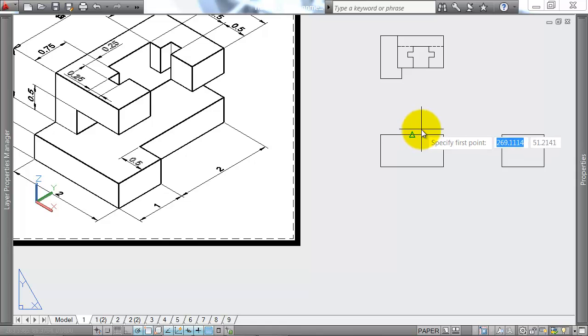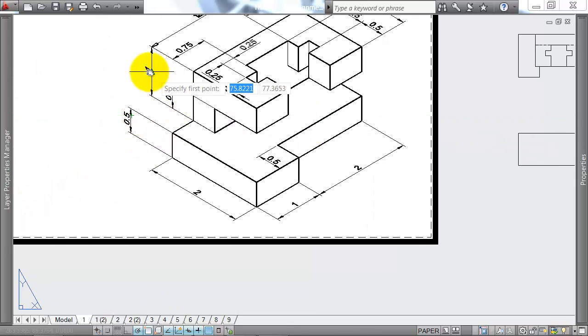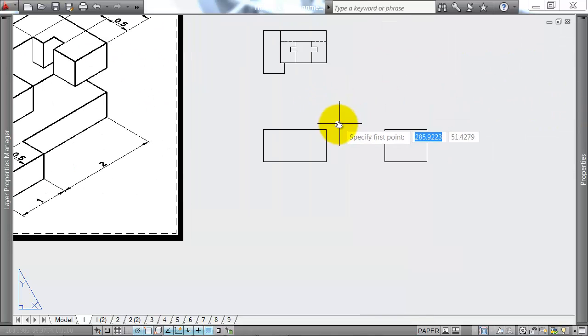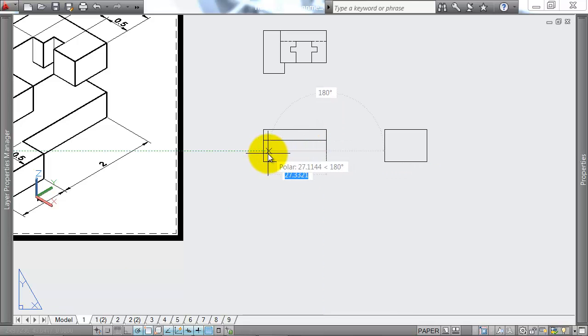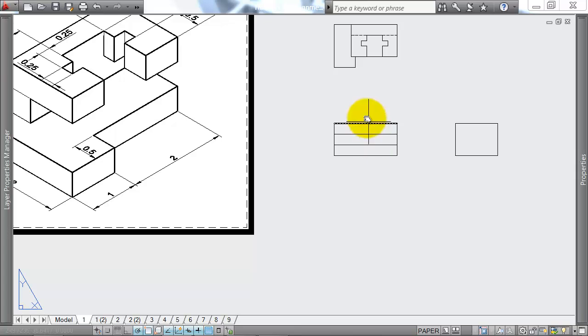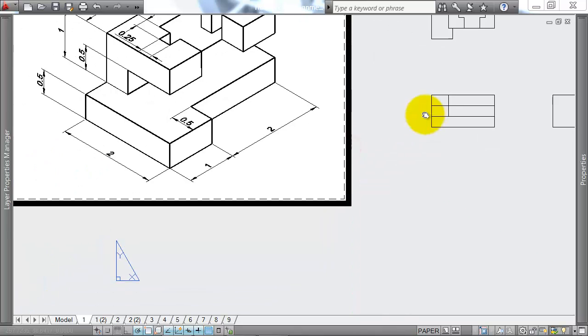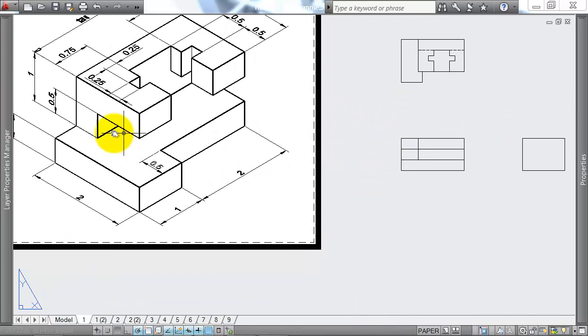Okay, so for the front of the shape, we've come up 0.5, 0.5, and 1 minus 0.5 is 0.5 again. So I'm going to go 5 and across. I'm just going to run these lines the whole way across. They wouldn't actually go the whole way across though. If I run this line down, they would end there. So these lines that are running across this top part of the shape are only as high as this 1 and 0.5 unit. Those lines I'm putting in there. If I trim off, I don't need this or this anymore. I can get rid of all of these lines. So my shape's going to go in here. The little toe part of the shape, that comes down like so.